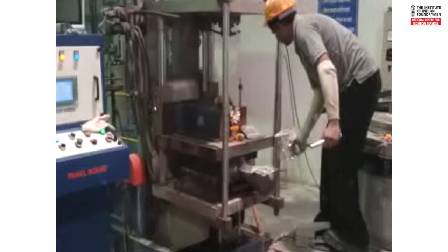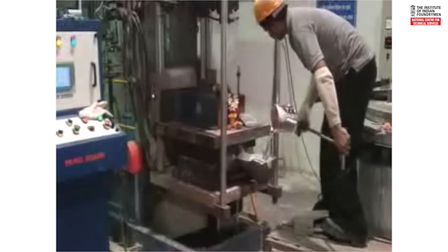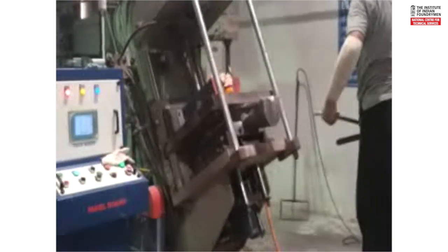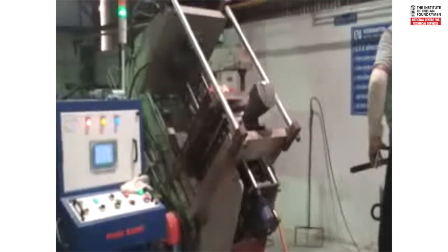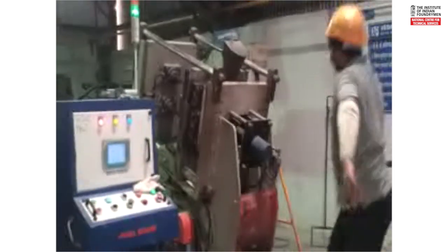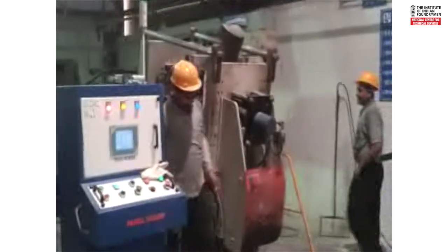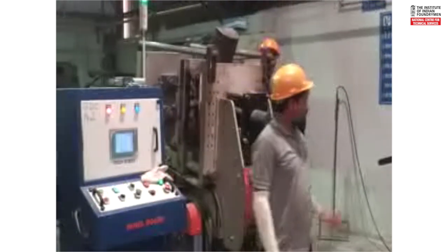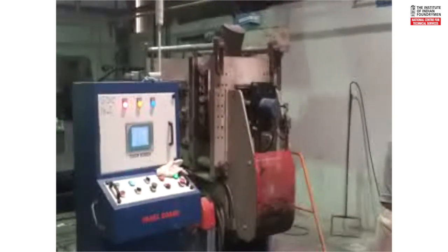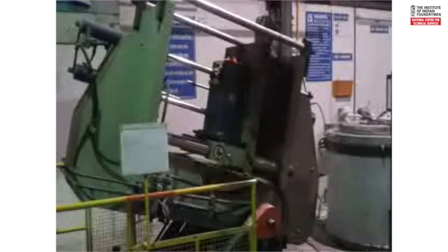The metal is poured in a saucer attached to the die and the whole assembly is tilted so that metal fills in a laminar flow. This delivers better mechanical properties and issues related to filling are minimized. You can control the tilting speed and fill rate both, thereby adjusting the directional solidification required for the component.